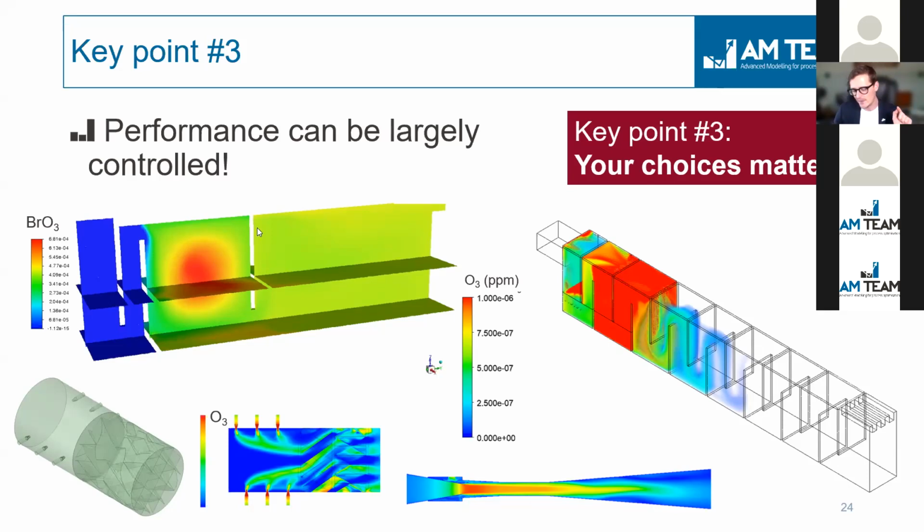And yes, if we model full-scale plants, usually we were involved in the design stage where we use CFD to help design the reactor. Based on exactly the same model outcomes which we used for the design, we transfer that to the environment Roberta and Giacomo have shown, and we construct a better model with it. So we have some methodologies for that. And this allows us to include residence time distributions in it very realistically.